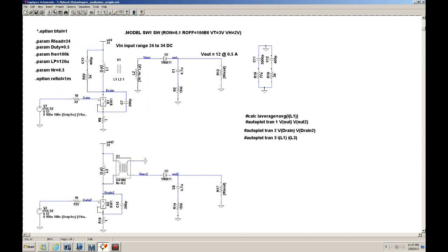But because they're global, I can have 2 or 3 of these defined within my circuit, and instead of changing all of those, all I have to do is define just one, and it changes all of them. So that's the advantage of using parameters: you can make changes like that globally.